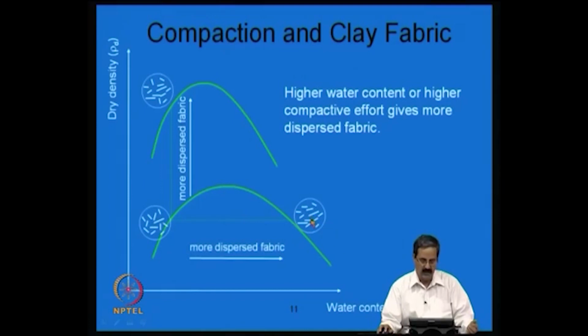So, for example, if you are talking about dams, nowadays the energy inputs are going to be higher, and permeability is an important factor in seepage and other considerations. So one needs to decide which side of compaction one should do in the case of, for example, a dam. Definitely it could be on the wet of optimum, where the permeability could be lower, so the seepage pressures could be lower.